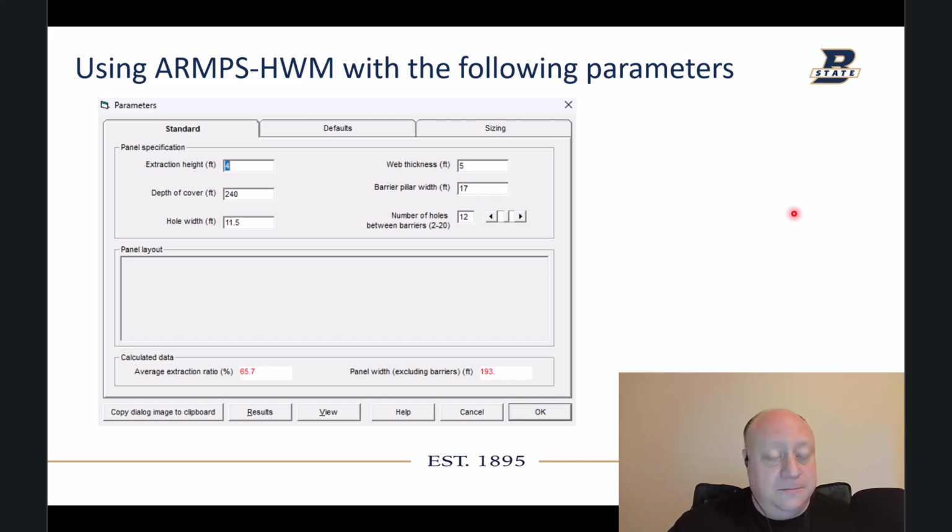about the extraction height. My assumption here is that it's going to be difficult to completely stay in seam at 3 feet thick. It might be possible, but it has a lot to do with how the seam dips, if there's any rolls in the seam, that sort of thing. That can very much impact your hole depth, and because you have this train of cars behind you, how well you're going to be able to stay in seam. And so for this, I assumed that we're not going to be able to stay in seam, and that we're going to have to mine it about 4 feet high.